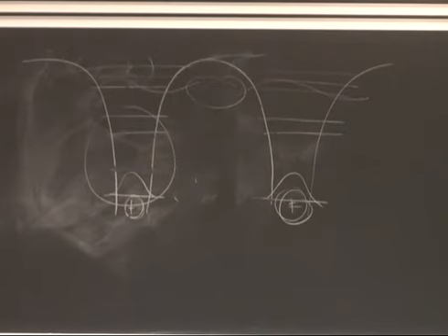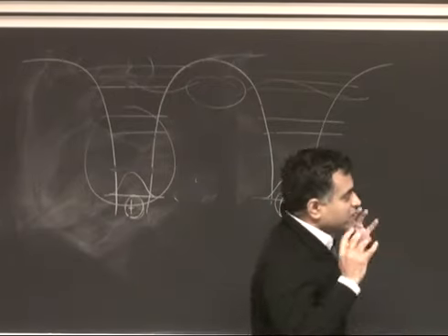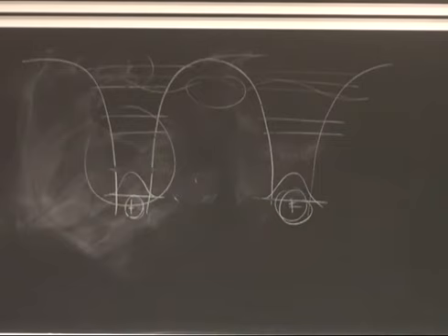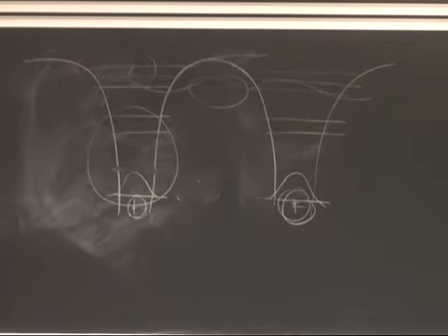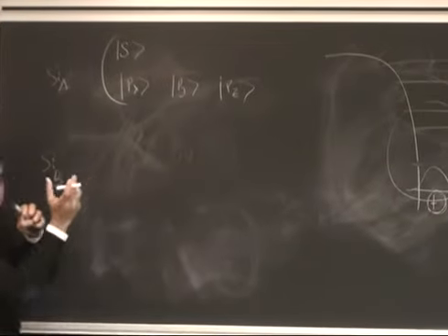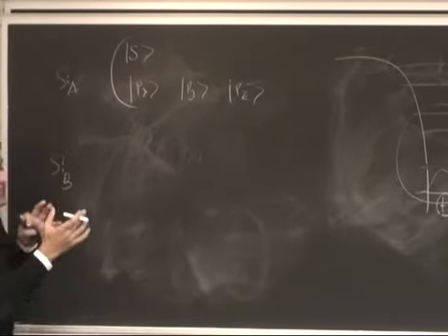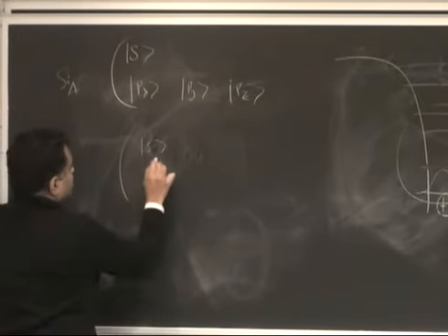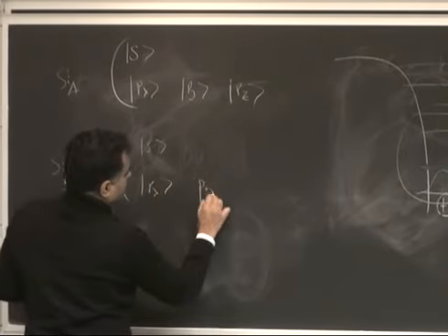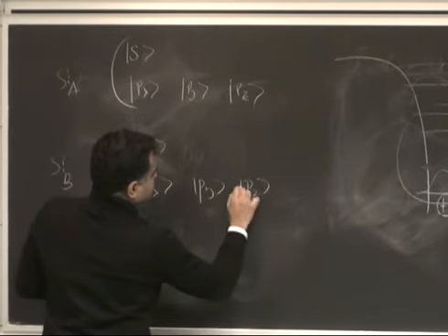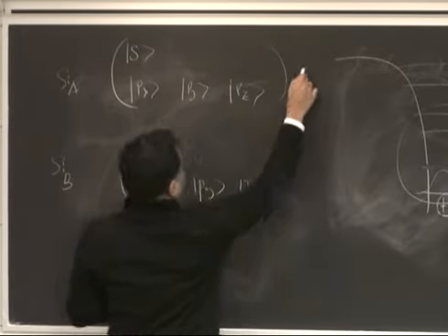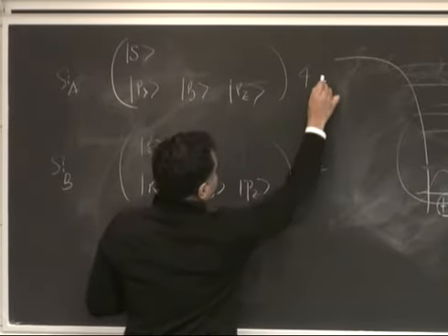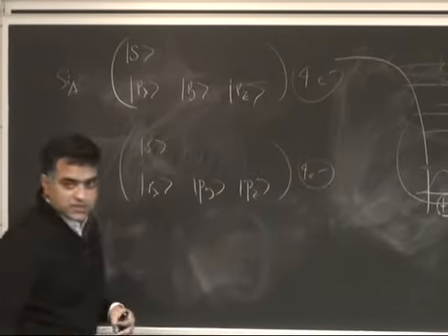Now this is the entire E-k diagram, the band structure of silicon. What we are going to see in the end is that the minimal repeating unit of the silicon crystal or gallium arsenide crystal has one silicon on the A side and one silicon on the B side. So there are 2 atoms that repeat. That's the minimal repeating unit for silicon, and each has again an S, Px, Py, and Pz. So there are 4 electrons from one side, 4 electrons from the other, a total of 8 electrons, right?